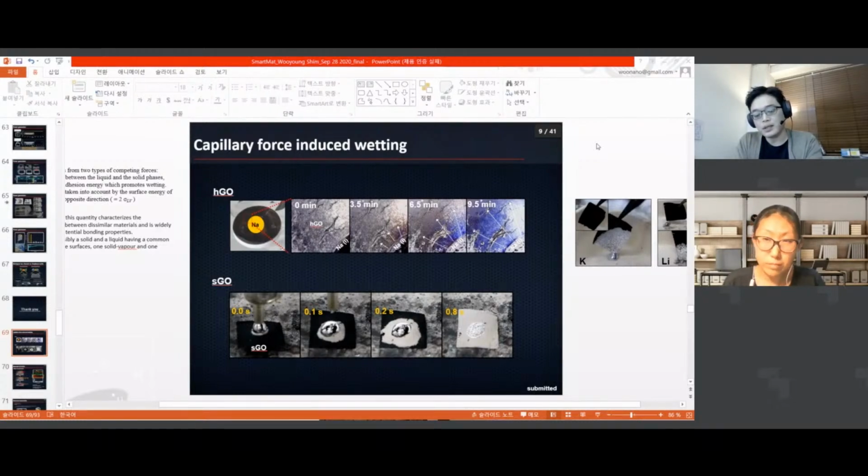But the other drawback is if you reduce the photoresist, you cannot deposit the thicker electrode, or due to the dry etching process, your etching ratio is not good, and you cannot define the well-defined feature as well. So the thickness of photoresist is very important. And some of the features I showed you, like the 50 nanometer best result, is done by less than 50 nanometer of photoresist thickness. So it's very important to control the thickness of photoresist. But in general, the quality of photoresist is very important as well.